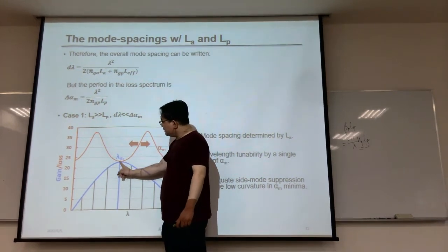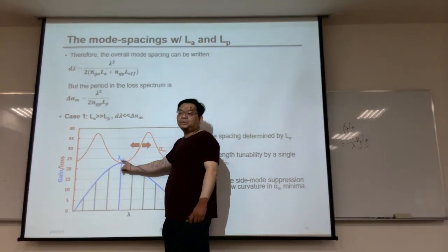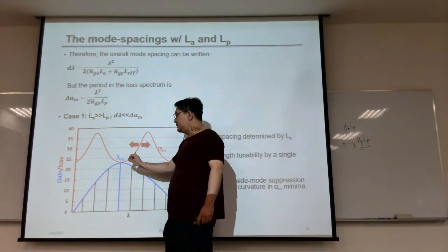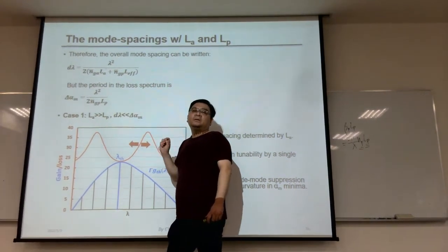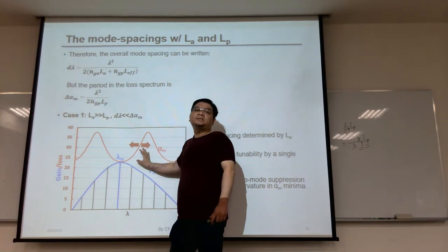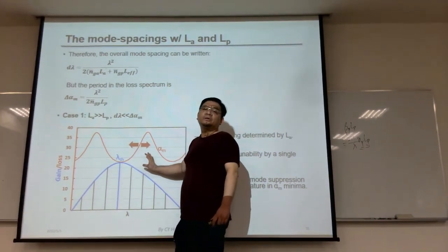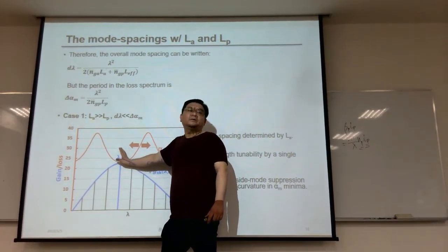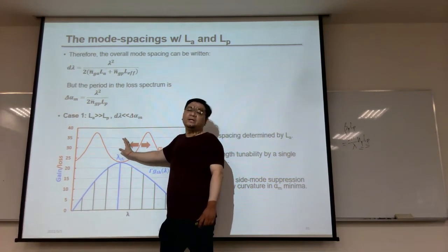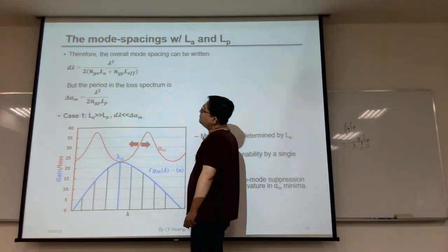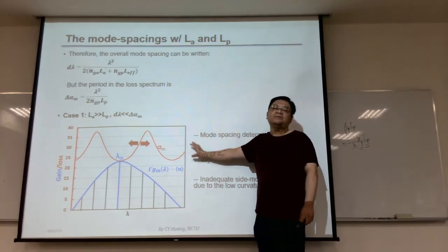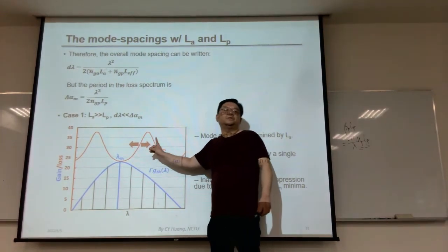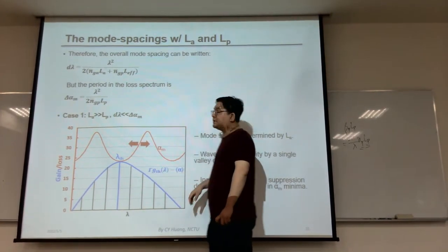So the intensity ratio between the principal signal and the side mode will be enhanced. So you get a better signal to noise ratio, if this mode is the only mode you require for communication. So the passive external cavity gives you a function of side mode suppression, which cannot be achieved with a single interface.